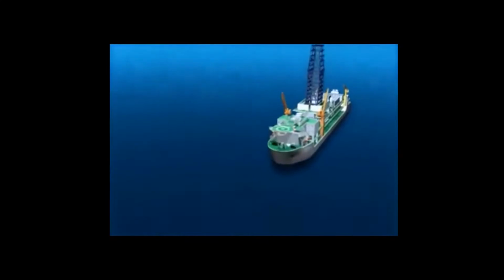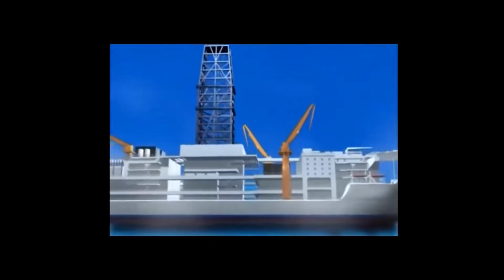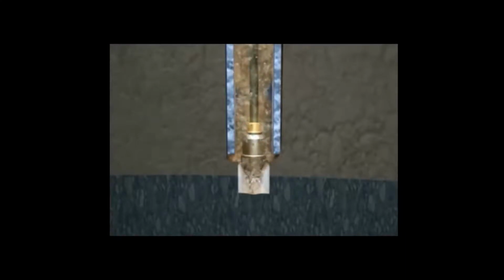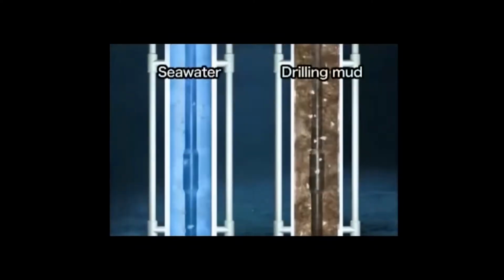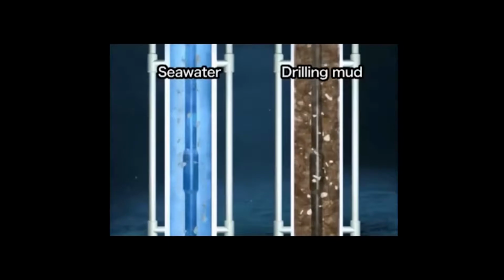The deep-sea drilling vessel Chikyu can drill over 7 kilometers below the seafloor into the earth. To drill even further below the seafloor, a riser system is used. With the riser system, mud is used instead of seawater. There are several reasons for using mud. First, it has greater viscosity than seawater to force cuttings up from the bottom of a deeper hole.